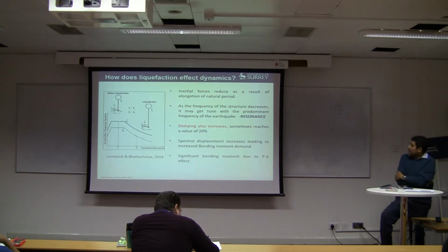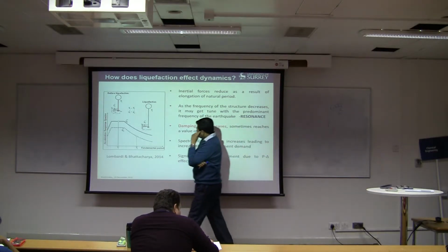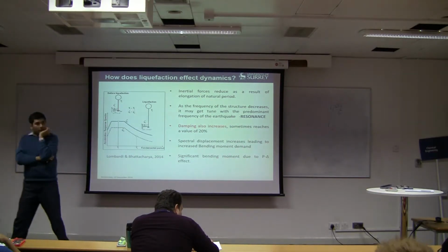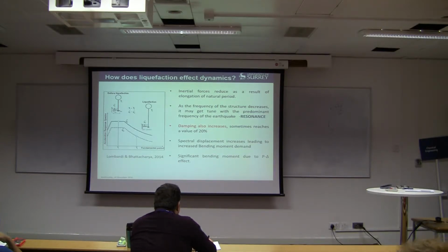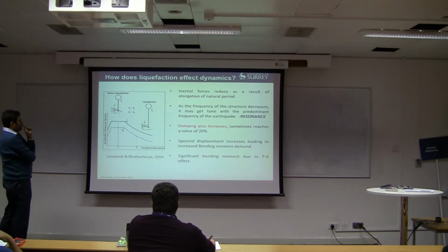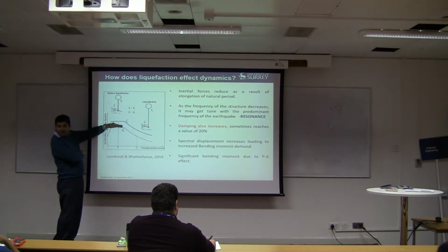In another sense, for liquefied soil, damping is very important. If you look at the response of a structure in an earthquake, damping plays an important role. That's the C term. You have a mass term, K term, C term. If damping is high, you get lower response.